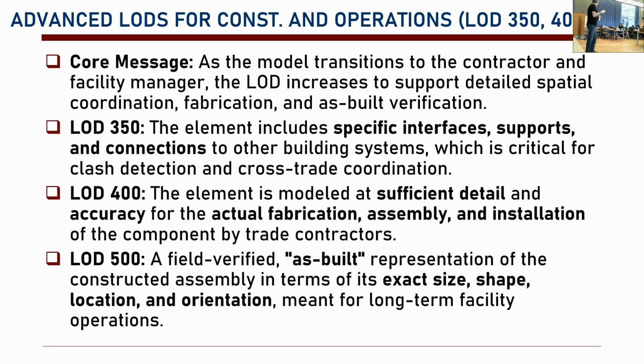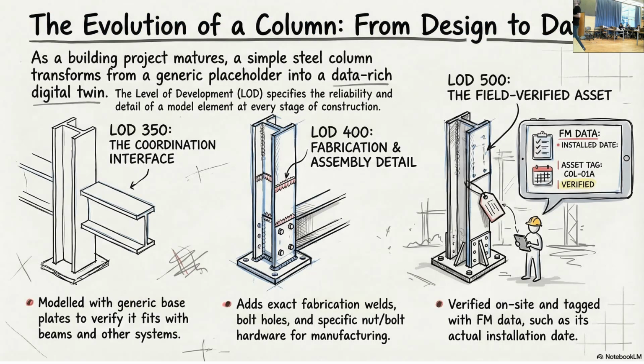In big projects, what they do is they also request laser scans or copies of the spaces. So they want to confirm that, for instance, there is a steel structure. With laser scanning, we want to know how much deviation we have from the project. 2 centimeters, 5 centimeters, 10 centimeters, we want to know, okay, because that's needed for the future.